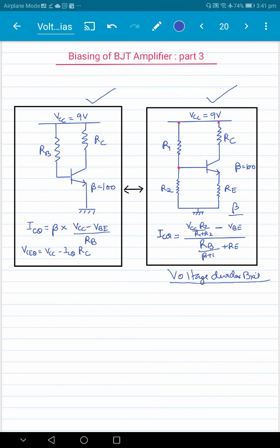In continuation of that thought, one of the key losses in voltage divider bias is that when you implement this biasing scheme, you end up losing gain, and you end up losing swing also. So besides more sensitivity to resistors and to base emitter voltage, you end up with these problems also.